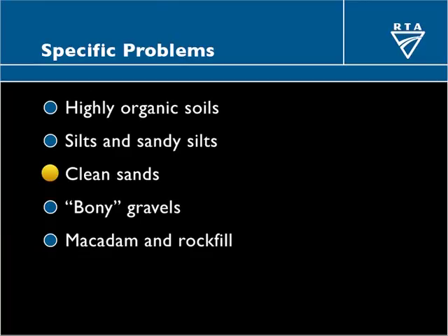You can stack that up vertically, cut vertical surfaces in it while it retains that dampness. That means it's got a lot of internal strength derived from the water films inside it and their surface tension. It also makes it very difficult to compact it very densely using any method, vibration, static, anything. So that requires a special technique. Bony gravels are much in the same sort of class and are often afflicted by poor shape as well.